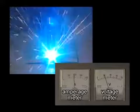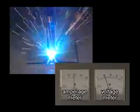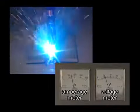In this way, moving the torch in and out causes undesirable welding results due to the changes in amperage, arc instability, and wire deposition rate.